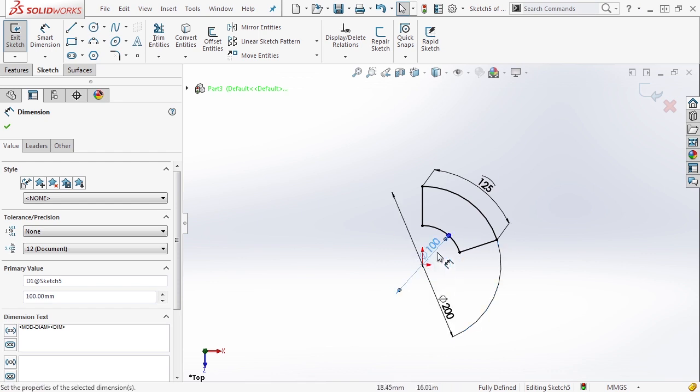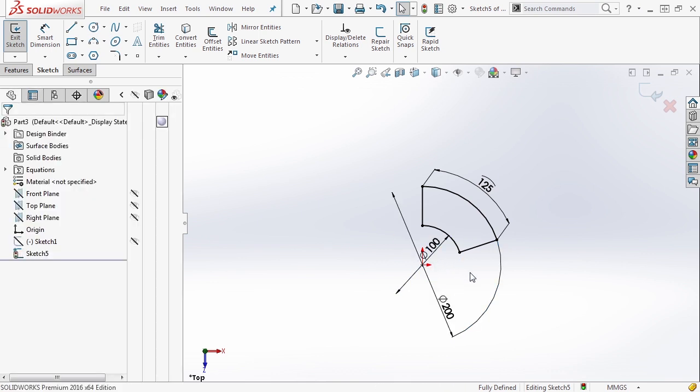One thing you'll notice when you start to use SolidWorks is that if you create very complicated sketches that have lots of dimensions driving them, one, they won't update properly. You'll have to go in and manually control all of those dimensions. And two, it'll be very hard to see through all of the dimensions. Of course, you can show and hide things, but in general, you want to keep all those dimensions on so you know what's changing. It's very important that you understand sketch relations and that you know how to use them and understand how they update your sketches.